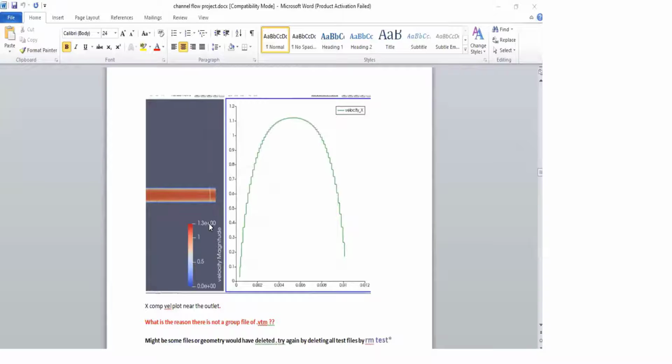So now this is where your flow will develop completely, and there are chances your flow might not get developed also. So if you want your flow to get completely developed, you have to check this out, and then you have to play with the boundary conditions, length of the pipe, and all these things. That depends upon what kind of things you are looking at.